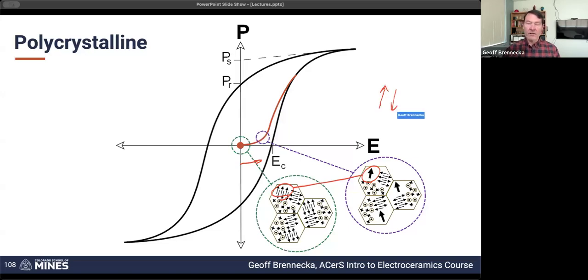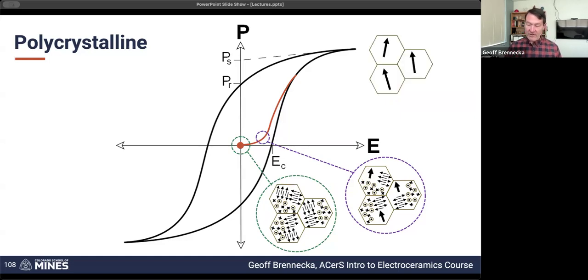because there's really not a heck of a lot of strain in this sort of scenario. If you've got the long axis, the C-axis of your tetragonal, and we're going to use tetragonal as the example, but you can extend this to any other low symmetry as well. If the long axis is pointing in the same direction, simply moving the ion from one direction to the other doesn't really strain anything. So these 180-degree domain walls are the first to switch because they're the lowest energy required to switch. So as we continue to increase the field, we will gradually get 90-degree switching as well.